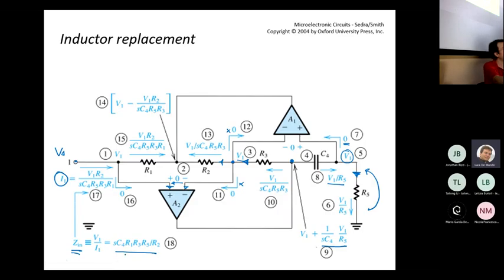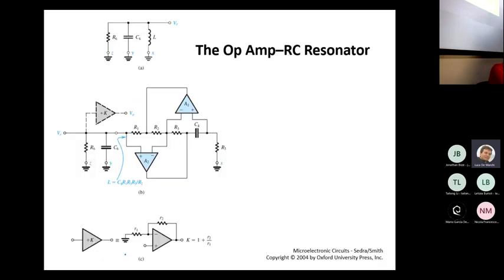So all this circuit is equivalent to an inductance. What we can do is to cut off the inductance from the schemes and the topologies that we have seen so far and replace the inductance with all these components. This is what is shown for the case of the generic resonator. So you remove this inductance here and you plug in the circuit proposed by Antoniou.